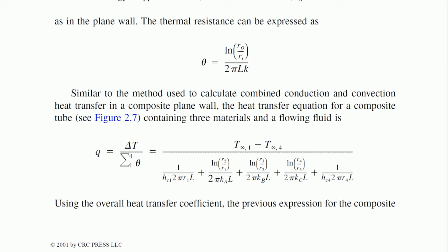The one we have made by gravity die casting and sand molds will be very poor compared to something which is pressure die cast. So, if you see all your motorbike engines and all, invariably all the items are pressure die cast. So, the conductivity is very high. In contrast to your experimental things, in case you have seen my earlier enclosure design lectures, I have shown you a video on a water cooled power electronics module which we are making. If I get a chance and if it is ready, I will show you a picture as you mill it, and if you come close to it, you can see that there are small voids. This is where this K invariably varies. So, experimentally you need to find out.